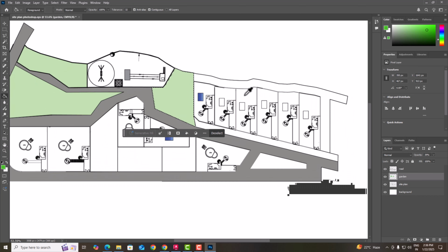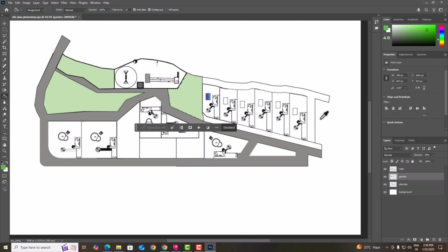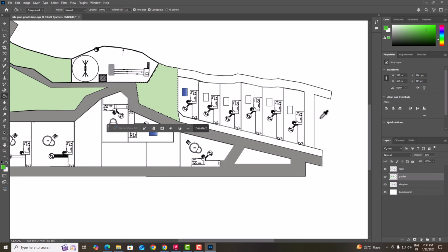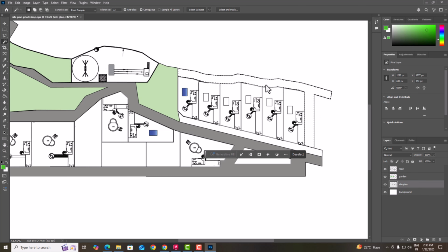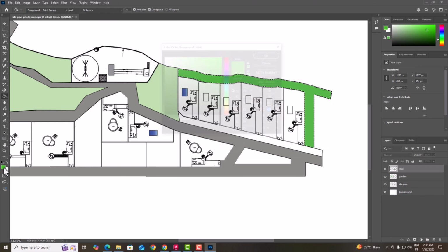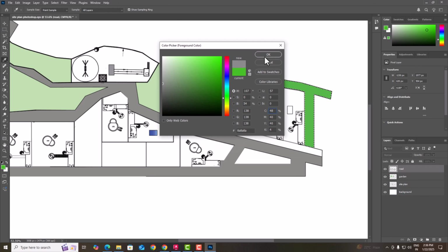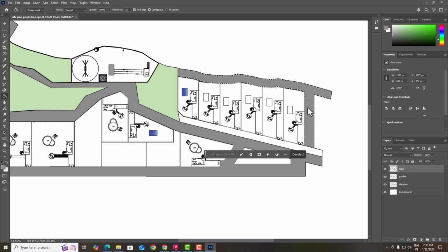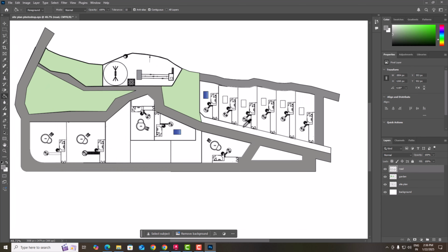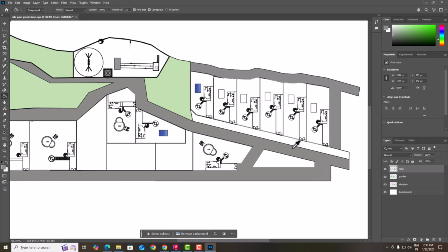And this is also road here. So you can apply a road texture here. I'm going to select site plan and the magic wand tool, and I will select the same road here, and I will press G command, and you can bring a similar color here. So these are our roads, and this is a side pavement area here.